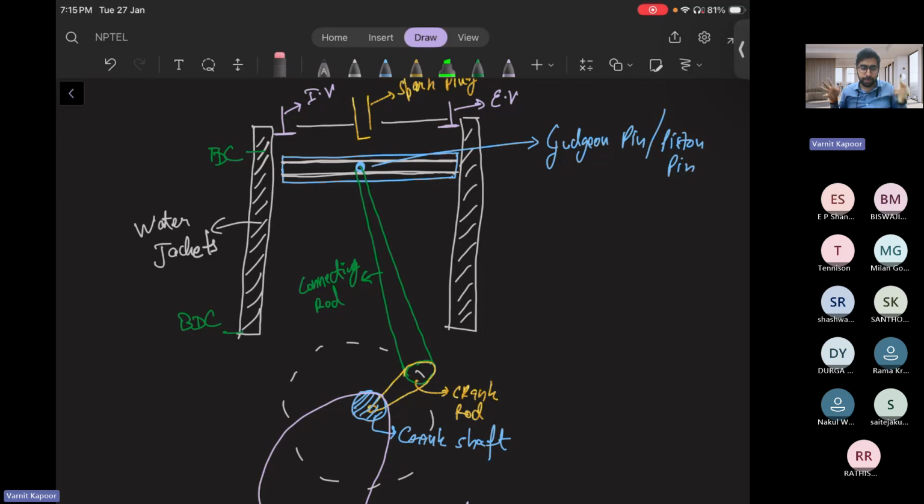So that means you are pressing it or dropping it so that all the defects and gaps inside the material go away, and it becomes a very high strength product. Then it is machined to remove surface defects, by brushing, milling, rolling, or whatever the manufacturing processes for machining are. So we can say that it is a very high strength forged steel material for the gudgeon pin.